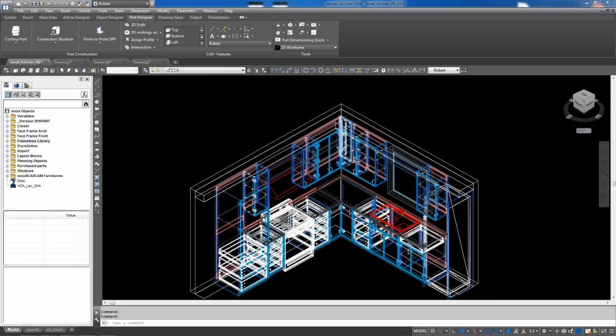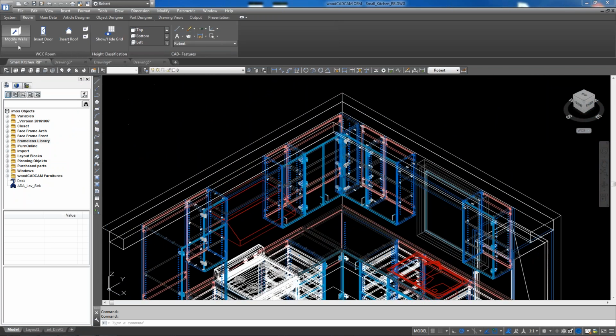I wasn't sure if this is something you create or install, like wall and pillar. If I can create it from a polyline, that's fine. Yeah, to me, I found that to be the easiest way to do a soffit. I can just create a polyline in the shape I want, make it the height, and put it where I want it.